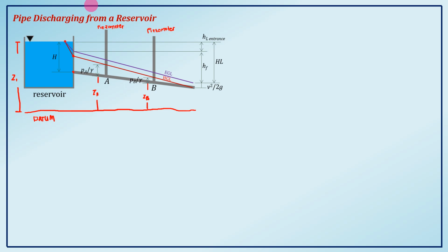That drop is due to the head loss again, the head loss at our entrance. This entrance head loss is an example of a minor head loss. When we say minor head loss, these are head losses that we neglect because they contribute so little, so we consider them almost approaching zero. Sometimes they are canceled out in our equation.